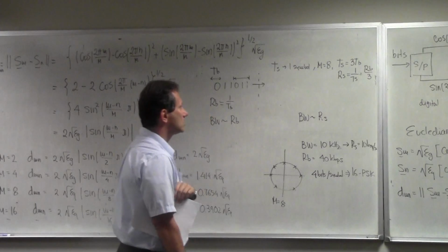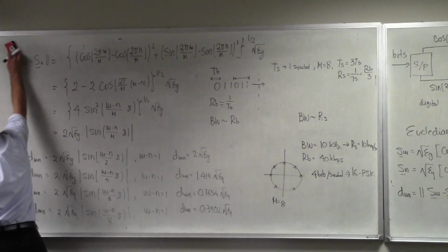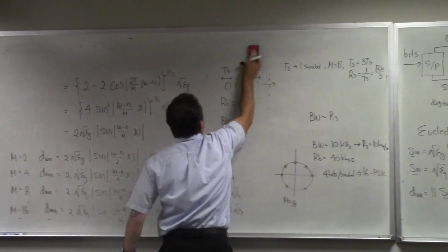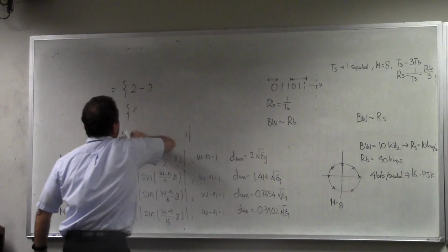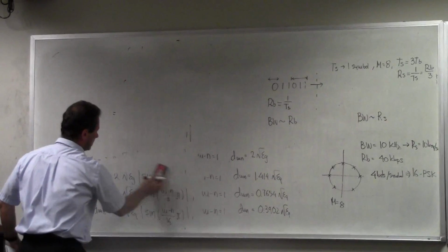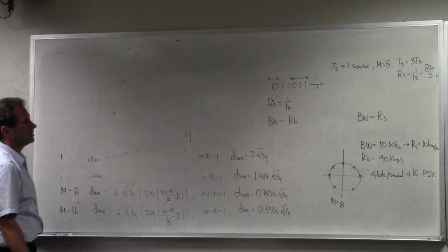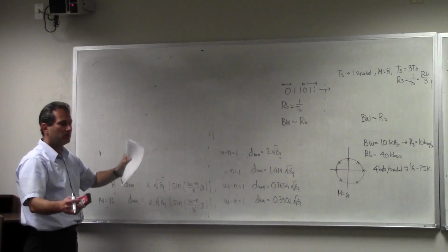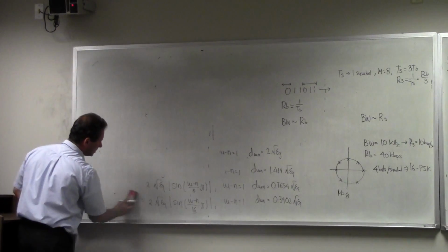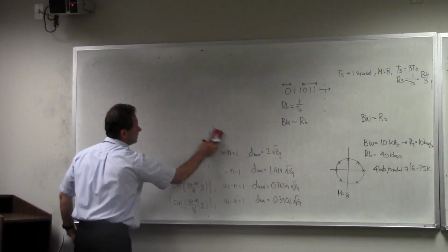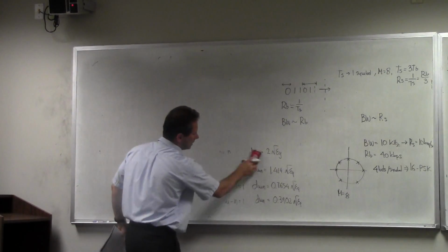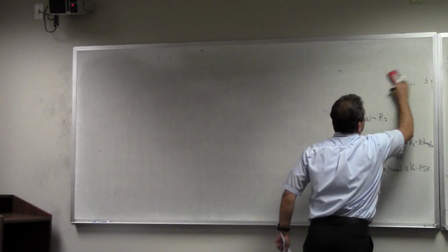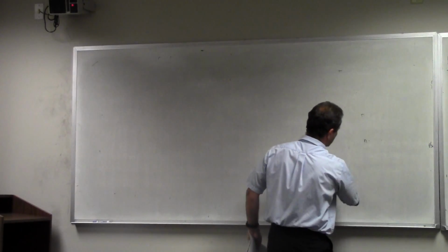So this is how we get to the concept of quadrature amplitude modulation. Quadrature amplitude modulation is actually more general than this. It's the most general, I would say, of what we call linear modulation schemes, which is this kind of two-dimensional signaling. As you will see, it will include PSK as its special case, but it will be more general and it will allow us to select some additional points, and therefore it has potential of being more optimum from, let's say, signal to noise or bit error rate standpoint. So let's just talk about quadrature amplitude modulation.